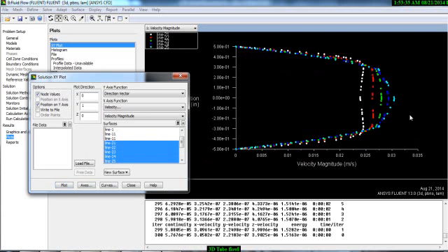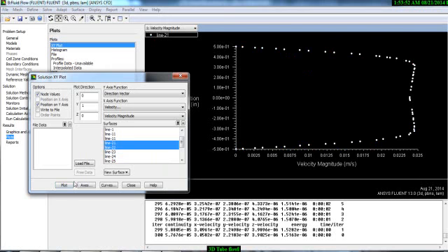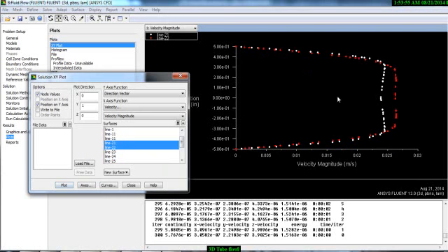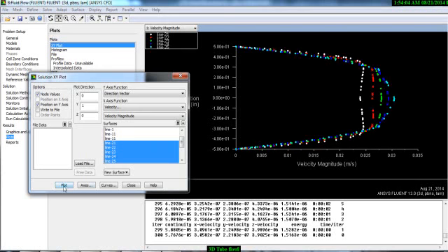So here you can easily see the velocity boundary layer and the velocity distribution. At 1 inch from the inlet, the velocity distribution is the red line here. At 2 inch from the inlet, it's developing. At 3 inch it's still developing but taking the parabolic shape. At 4 inch and 5 inch it's perfectly parabolic. So you can see the momentum boundary layer and the entry length. So this is the process.